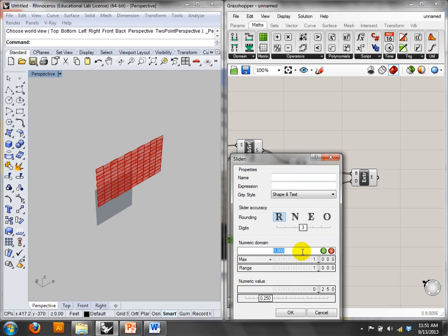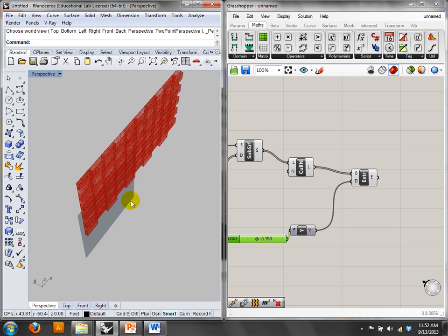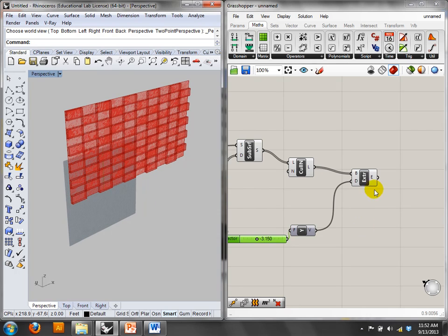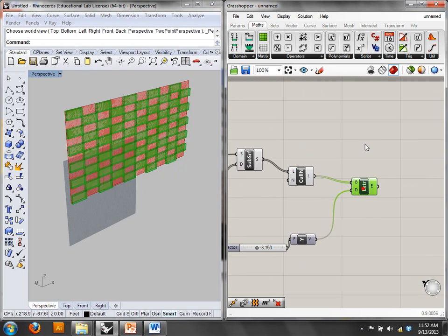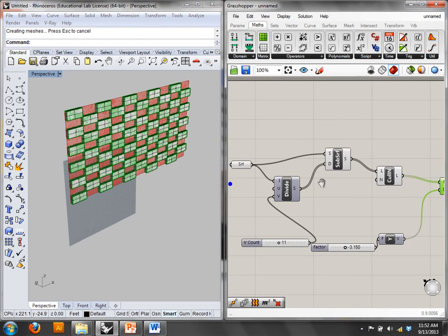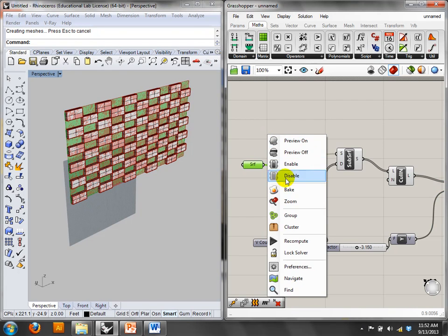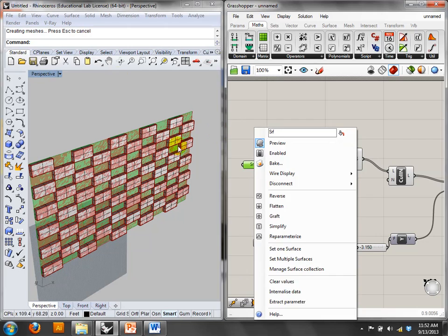If you don't get it right, you'll figure it out because you can just see it and then change it. But it's good to know ahead of time if that's what you want. So again, if I extrude that outwards, and I may have talked about this, but if you want to get something in Rhino, you actually have to bake it first. So if I bake this geometry,